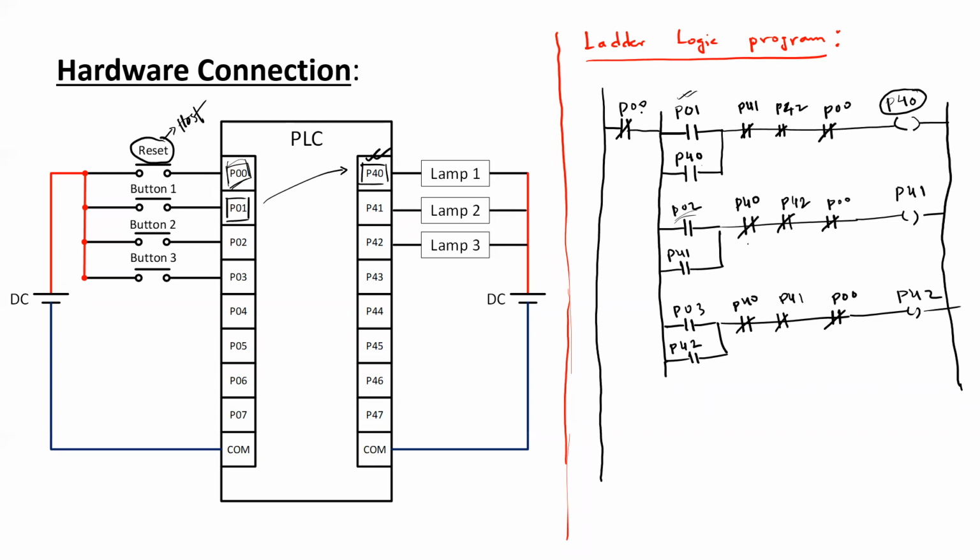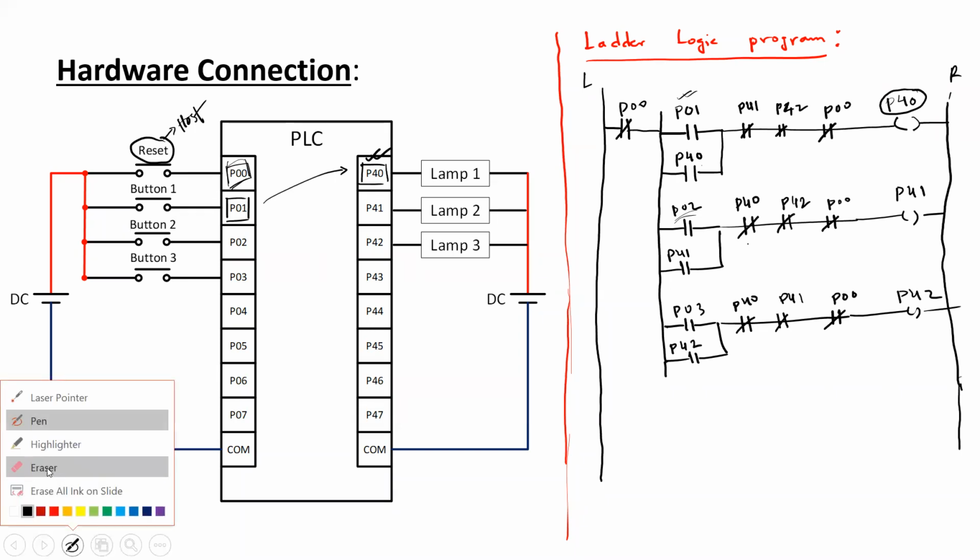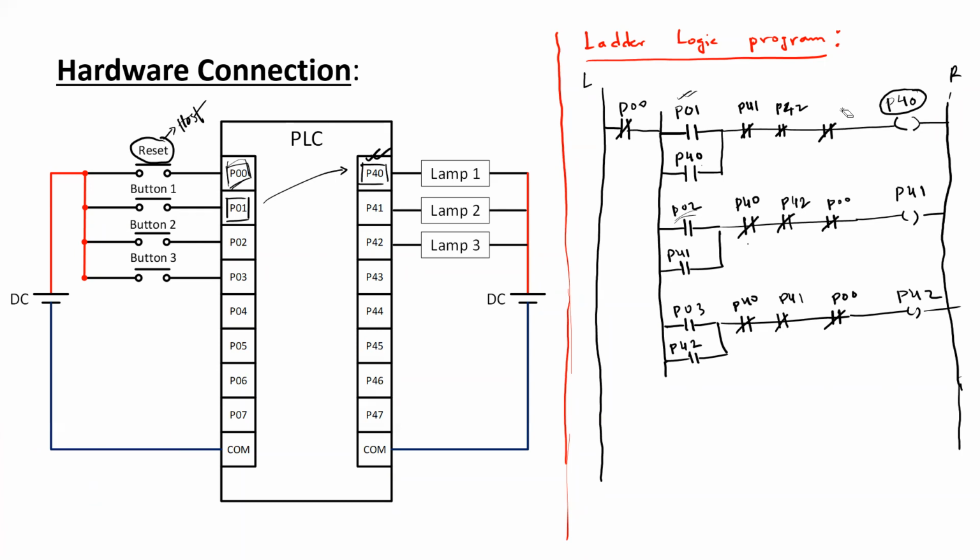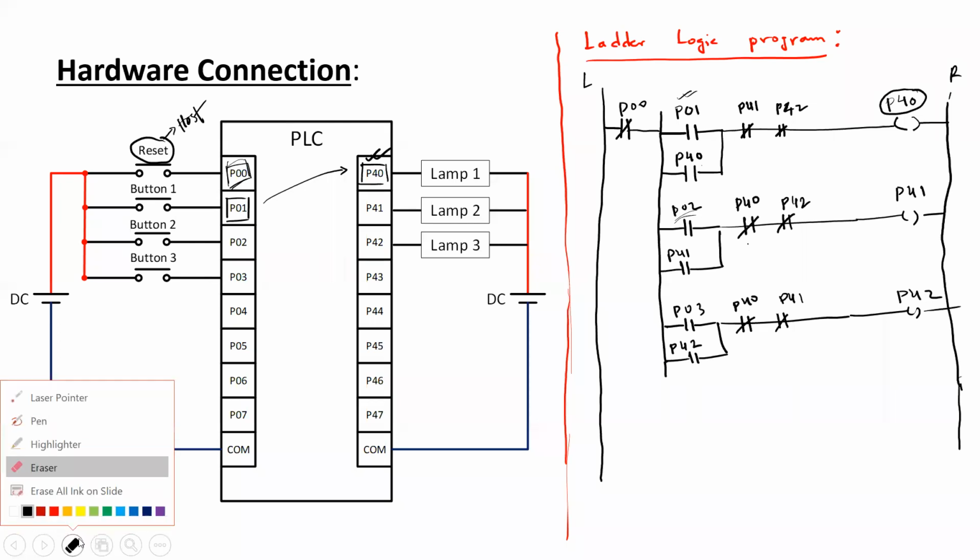So that is actually going to do the same task because it is going to disable the entire circuit on the right hand side portion from the left hand side rail, and it would not be necessary to put separate contacts on each of the individual lines. So both of the options will work here. However, the second approach could be better to adopt.